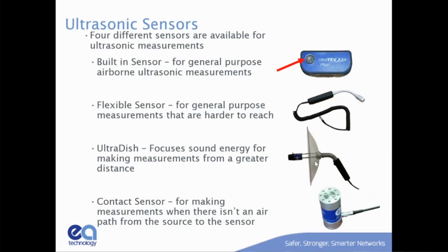The parabolic dish is great for looking at stuff on the ground. It's at about 30 feet. It's got about a 1 foot spot, so you can use it and work it up and down insulators or cable terminations on a riser pole, that sort of thing, and look for PD without getting in a bucket truck.